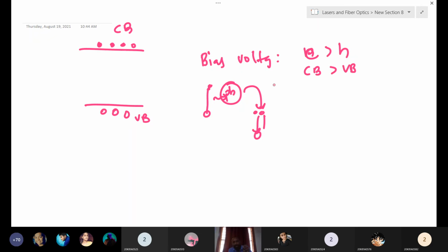These photons trigger the remaining electrons to come to the valence band and recombine. Once they recombine, we emit photons. Like this, photons will emit. One side of the laser junction will be cleaved to block the surface, and only the other front surface will give the laser beam. This way we produce it.